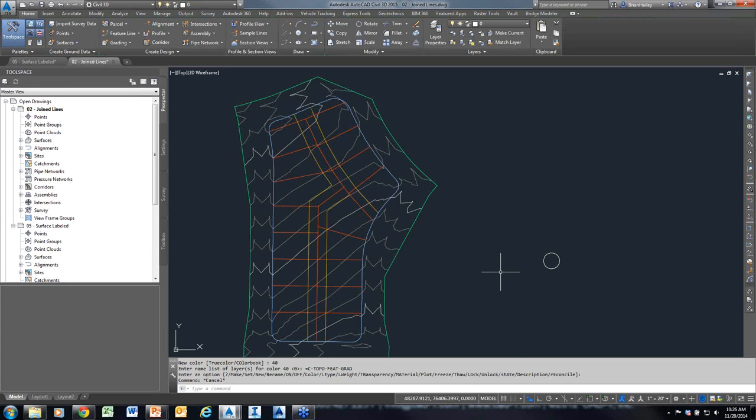There is some other things you can do with feature lines. The styles. So in that other example I had where the two feature lines crossed, you can actually control which one wins based off of the style. Now, in my opinion, you should never do that. Anytime you have feature lines crossed, you should always put a vertex there.